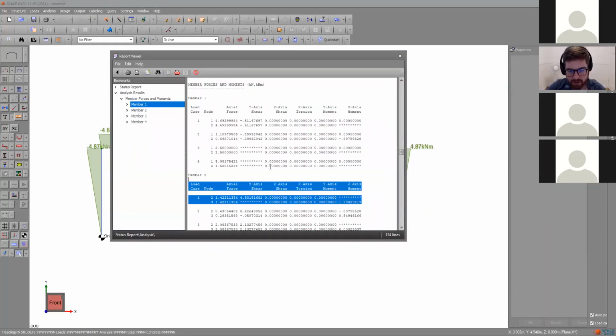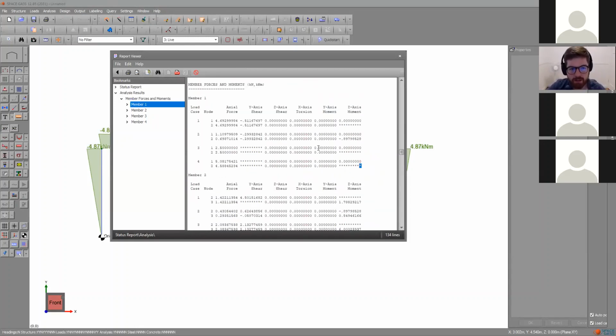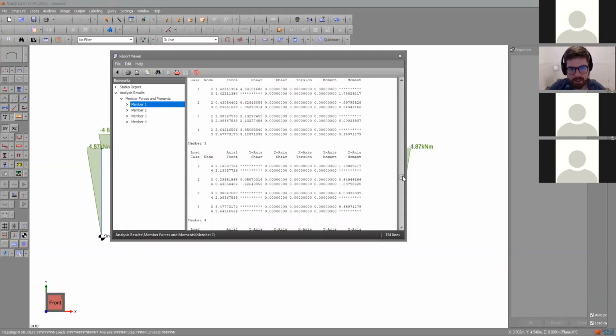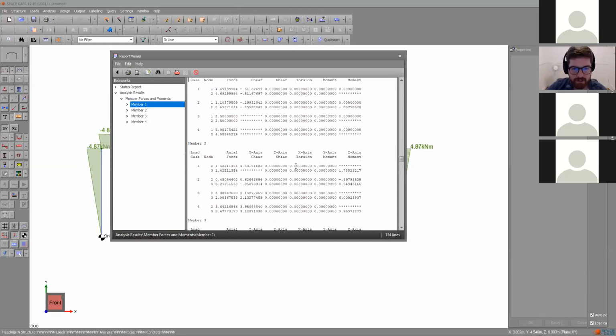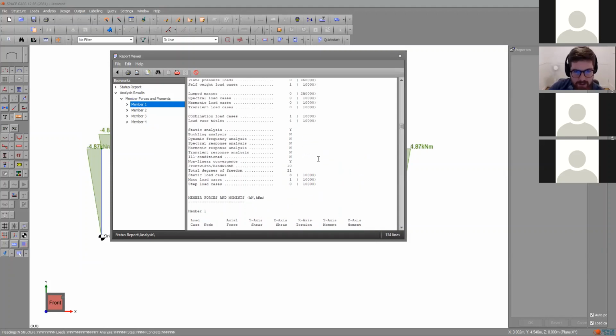And now this is the kind of thing you can copy paste into Excel, or you can open with Python as a CSV file or something like that, and you can actually batch process what the governing loads are, or what the minimum maximum moments are that I have to look at. Again, though, that's getting pretty advanced, and I wouldn't expect you to need that as an undergraduate, but it's a useful capacity for the future when you start getting into larger analyses.